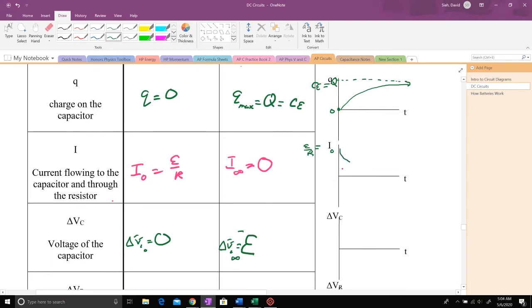You say, well, technically forever to push the last little electron off. To get the last little charge to the plates, right? You say the last one is going to take forever, because the force pushing it gets smaller and smaller. The E field gets weaker and weaker as the delta V approaches 0, and I get less and less pushing the charges to the plates. And so fully charging the capacitor is going to take forever, with just this trickle of charge flowing to it. So that's the idea. Hey, and we got the initial value.